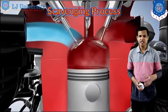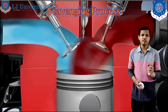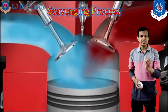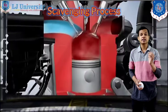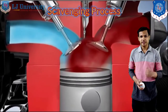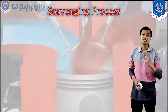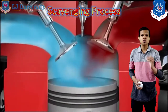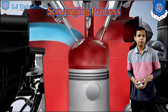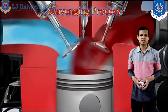Mostly in the case of the two-stroke engine, there is the valve overlapping that we saw in the earlier videos, in which the transfer port and the exhaust port are open simultaneously. So both are open at the same time, and there are chances that the inlet charge goes outside with the exhaust gases via the exhaust port. So in that case we require the scavenging process.